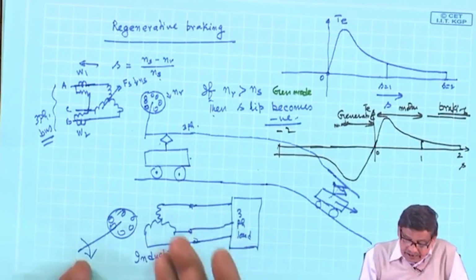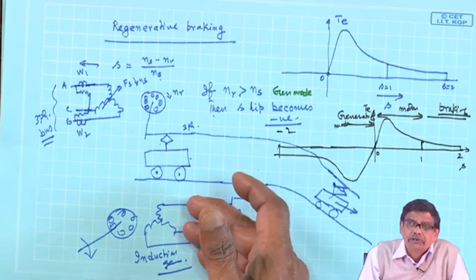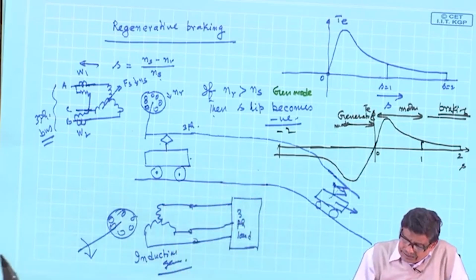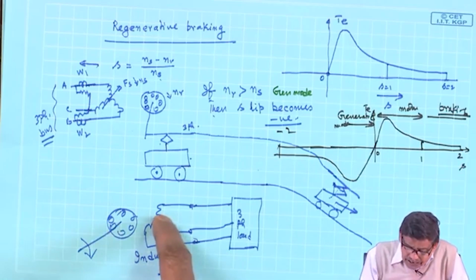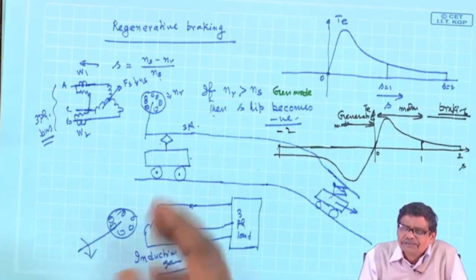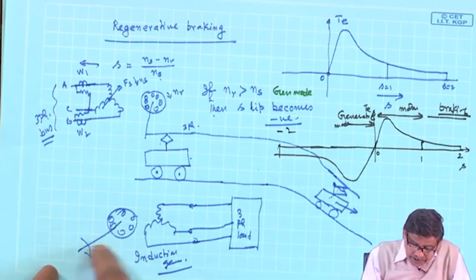IM is necessary. In this machine, what happens? Will there be any voltage? Do you expect here? Yes, I may expect some voltage if you run the rotor, because of some residual field here. Some residual field was remaining on the stator iron, rotor iron, and you are running the rotor.